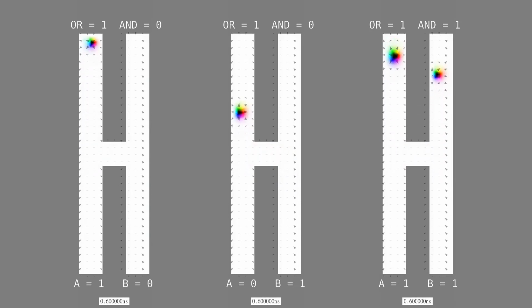You can see how the skyrmions are travelling through the gate in each of the different input combinations to arrive at the correct output. Due to the in-plane current, the skyrmions travel vertically upwards, and they also have a horizontal force pushing them to the left. So in the 1-0 case, the left skyrmion travels straight. In the 0-1 case, the right skyrmion travels left through the gap into the left channel, and in the 1-1 case, they repel each other at the crossing to stay in their original channels.